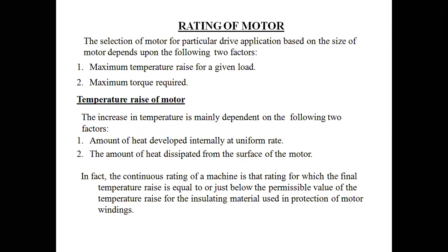Before going to learn about these two factors, let us see how the motor is going to be taken into consideration. The temperature rise always depends upon the type of insulation used. First of all, we have to measure the temperature regarding your particular application of the motor. So the size of the motor depends upon the type of insulation. What is temperature here? The temperature happens due to the losses that occur in the motor.